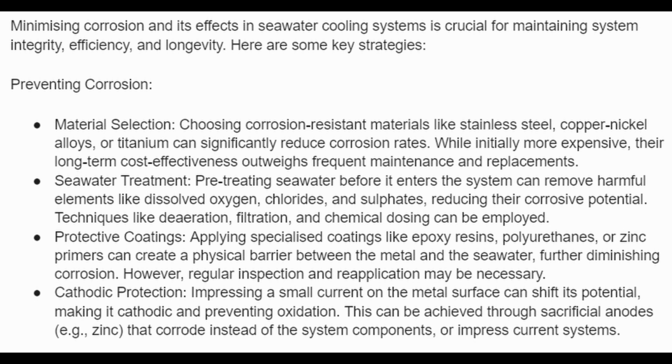Protective coatings. Applying specialized coatings like epoxy resins, polyurethanes or zinc primers can create a physical barrier between the metal and the seawater, further diminishing corrosion. However, regular inspection and reapplication may be necessary.